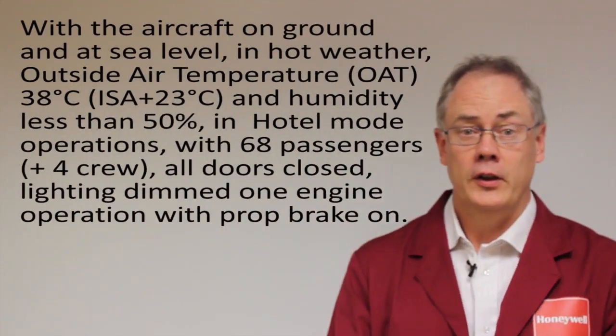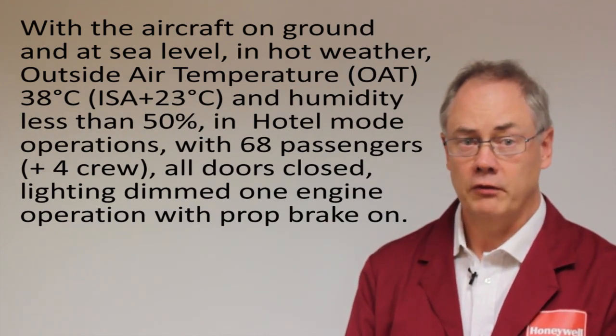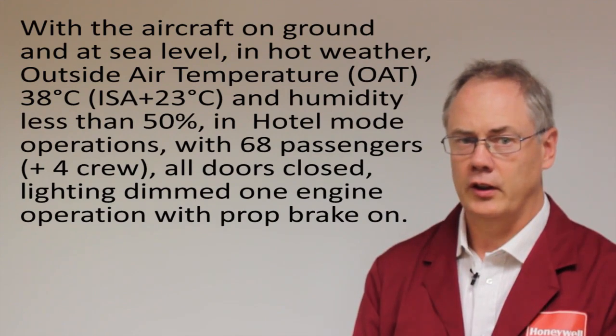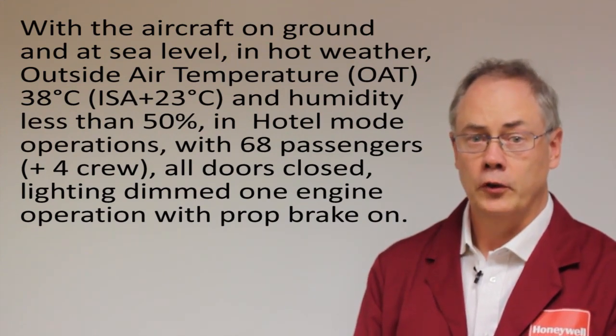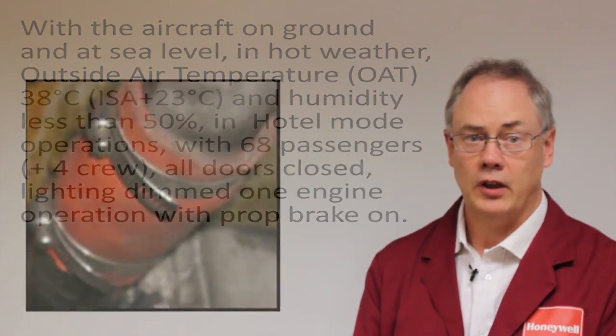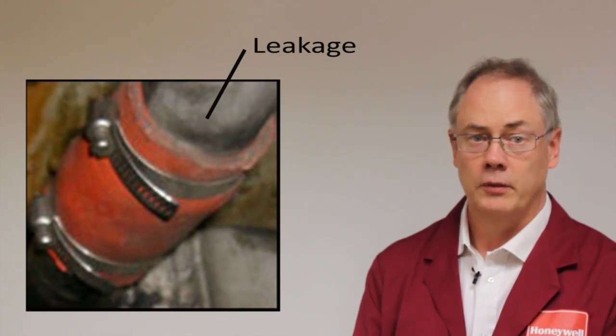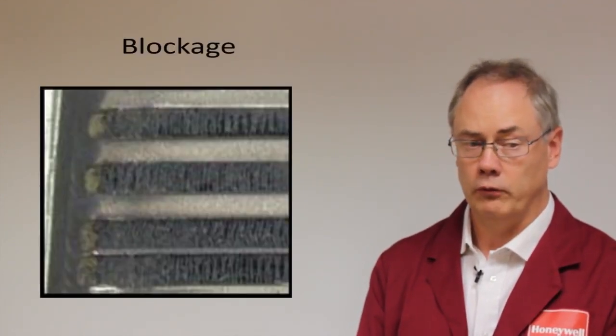Let's start by taking a look at some system performance capabilities. According to the ATR 42 and 72 technical specifications, along with these assumed conditions, the air conditioning system shall maintain a temperature difference of 8 degrees between the cabin and the outside air temperatures. The two factors most often resulting in performance degradation are leakage and blockages. Leaks and blockages may also reduce ECS component reliability.